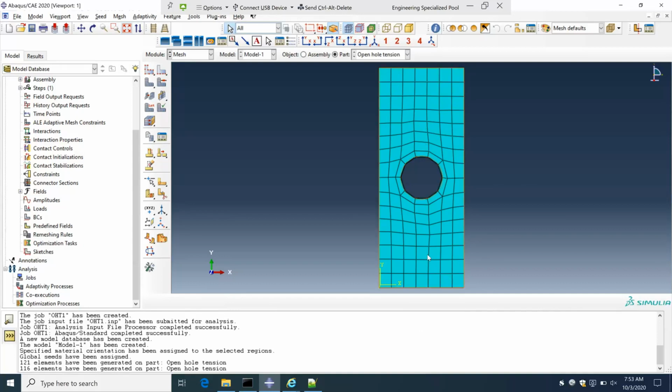So if you want to regularize the mesh in order to get a better solution, remember we have talked about stiffness matrix and how the process of inverting the stiffness matrix can be cumbersome if there are elements of the stiffness matrix that are too small or too big compared to the others. Then we will have a hard time getting a solution that is more accurate.